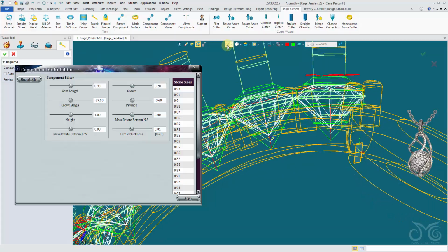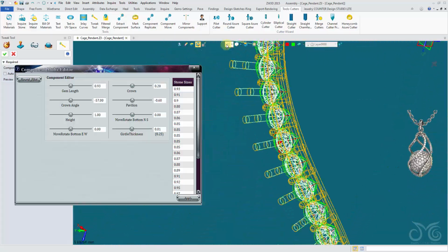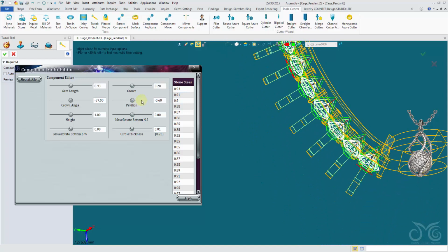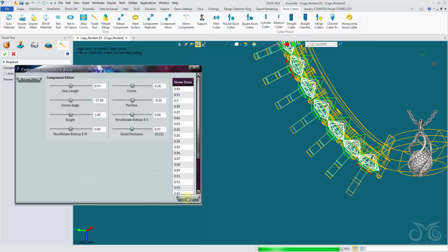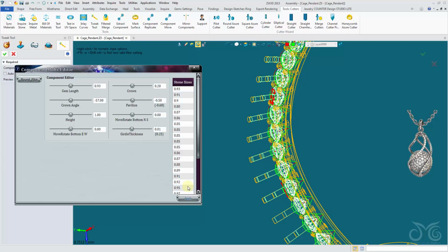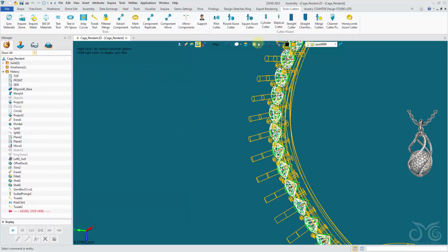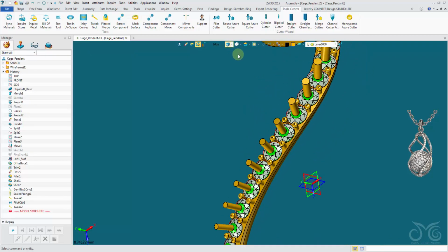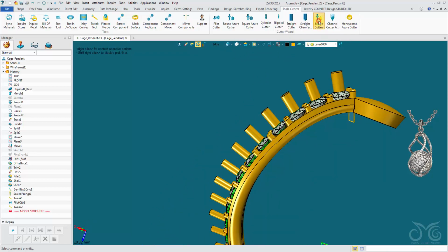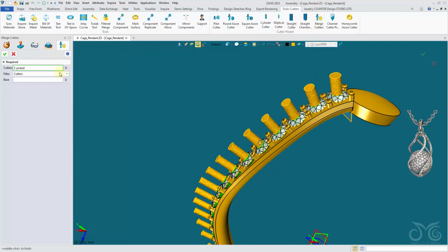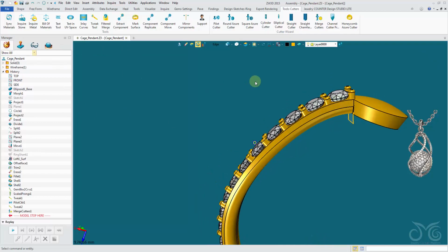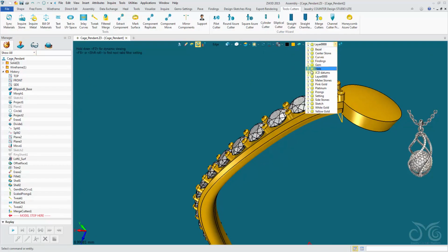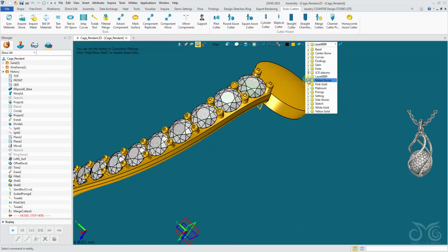Let's take a look first of all actually, if our cutters are getting a good depth there. Again, they're going plenty deep enough. Might even want to reduce that. The pavilion, let's reduce it to negative 0.5. Okay, we'll confirm the operation here. Let's merge our cutters. Let's hide our melee stones to check out how the cutters have performed. Okay, it seems decent enough.